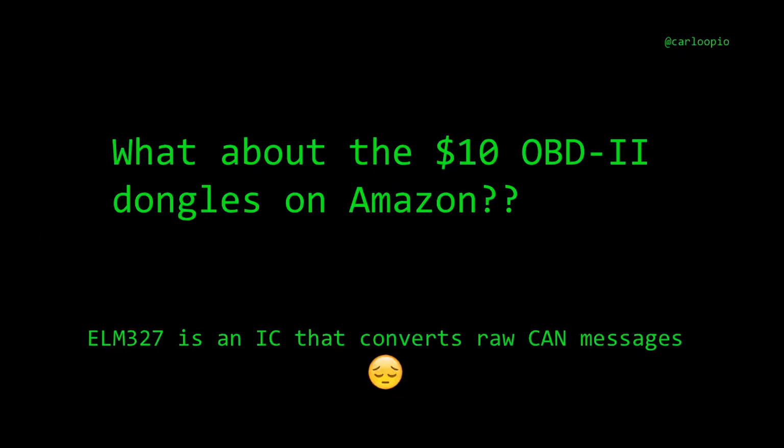A lot of times I get asked, what about these $10 OBD2 dongles on Amazon? Why can't I use those to hack my car? Actually, you could. It just takes a lot of work to use the tools, because they have an integrated circuit called the ELM327 that takes the raw CAN messages and converts them into actual values from the engine.